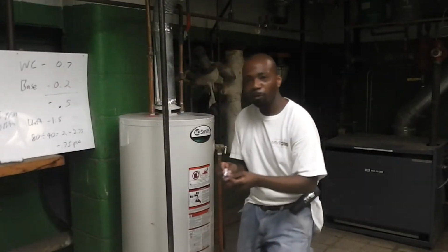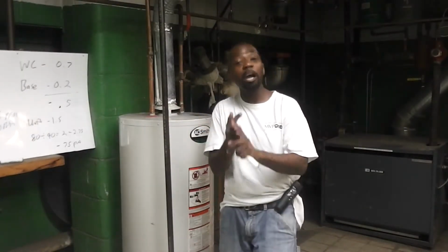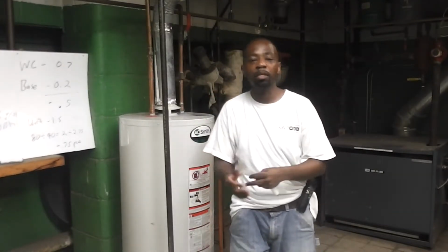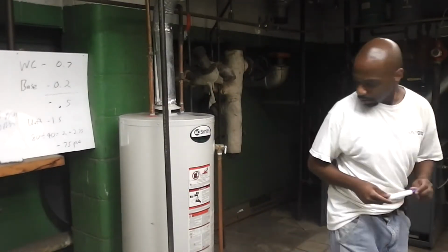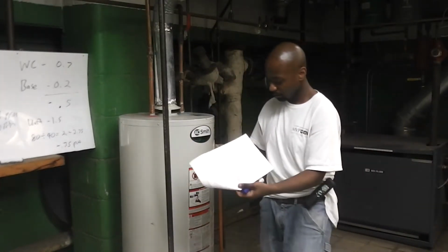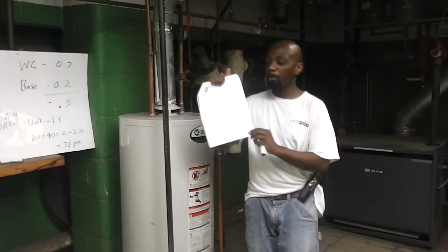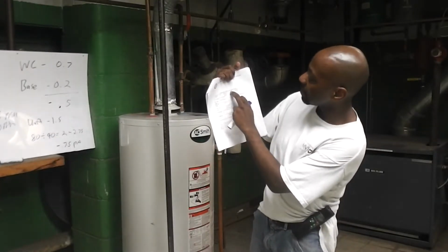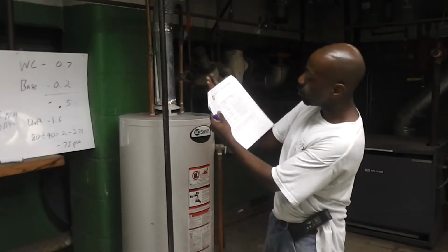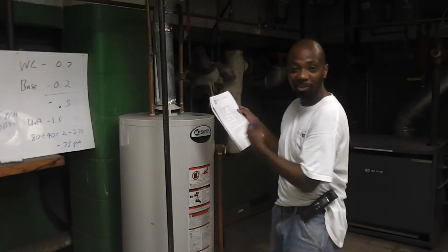So what does all this mean? So far we ran 4 tests. Our worst case, we passed, the spillage we passed, the draft we passed, and the actual CO this thing's producing was roughly in the 20 range. Let's see what it tries to say about this. Where's my chart? The chart I'm going to refer to is the combustion safety test action levels. This is page 13 of the standards. So we got about 20. So I'm going to the range of 0 to 25 ppm. That's pretty much the range of what we got.